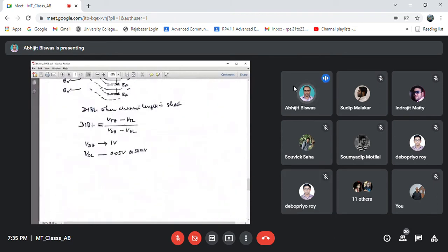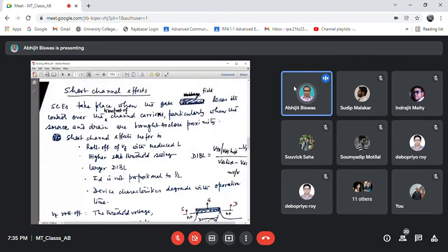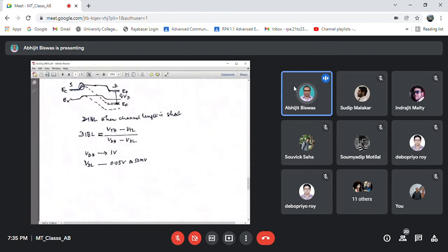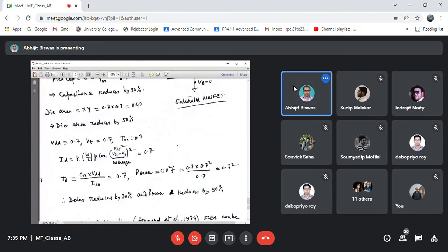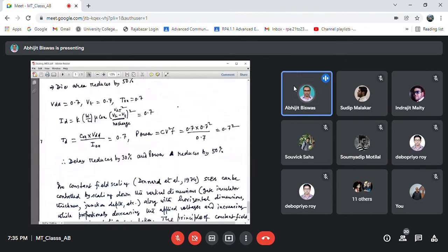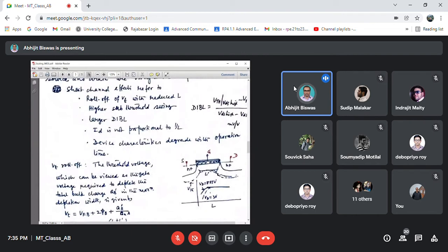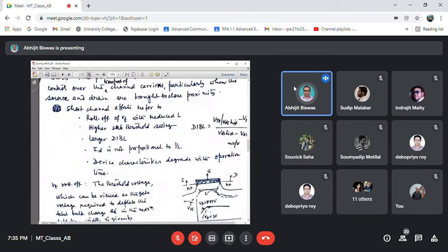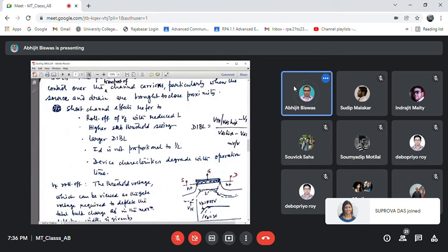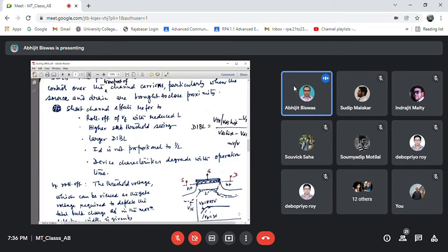Okay. So today I discussed these short channel effects and their consequences and scaling, downscaling, and also constant field scaling. You can also mitigate the disadvantages of short channel effects by several means. One is halo doping. That means in the source channel junction, you can create some pockets and dope them heavily, so that the electrical channel length becomes almost equal to the metallurgical channel length.